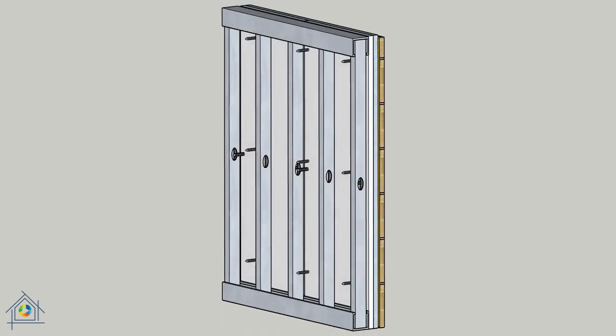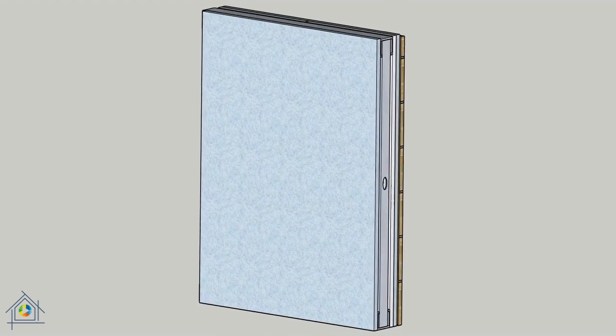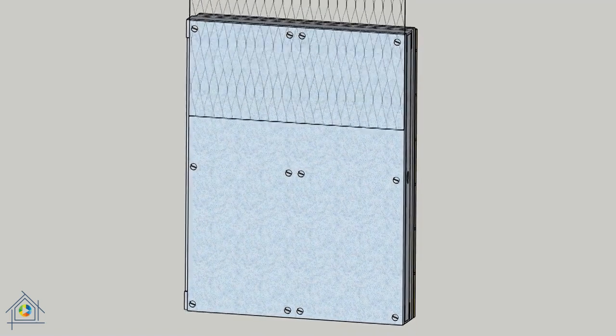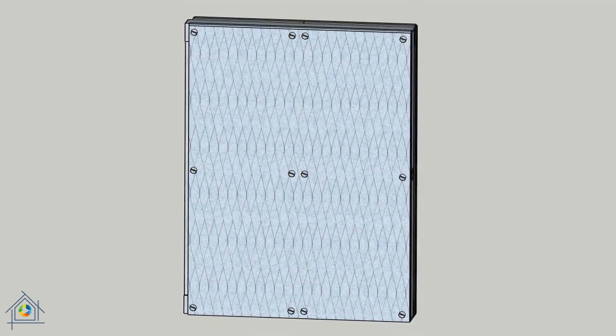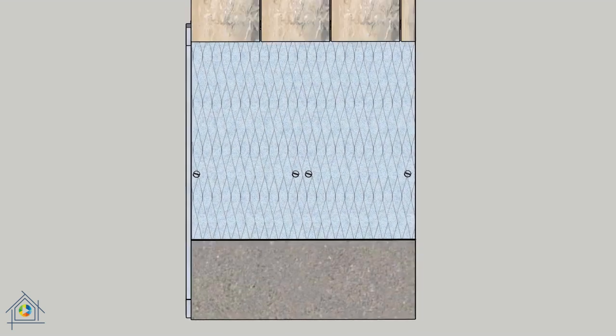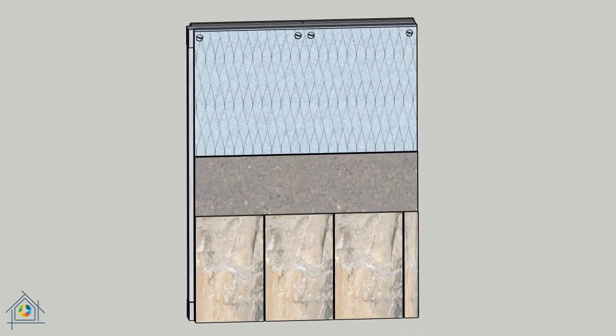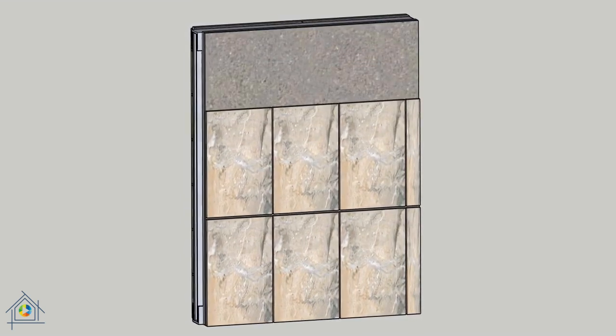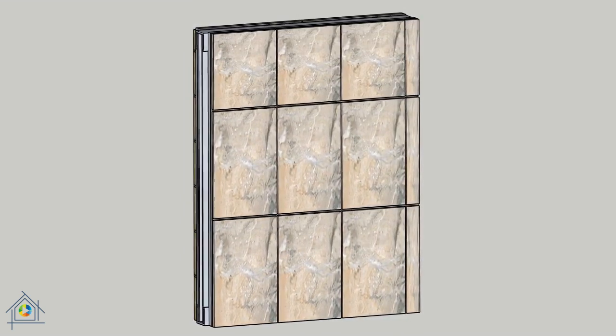On the outside of the building, first the moisture-proof prefabricated gypsum board is installed. Then, for the proper connection of the cement sand mortar, which is applied to connect the stone tile for facade to the wall, the rabbet fencing is properly attached to the prefabricated gypsum board. The stone tiles are attached to the wall using cement sand mortar in a volume ratio of 1:4. The mortar thickness is about 3 centimeters and is applied in 2 to 3 passes.